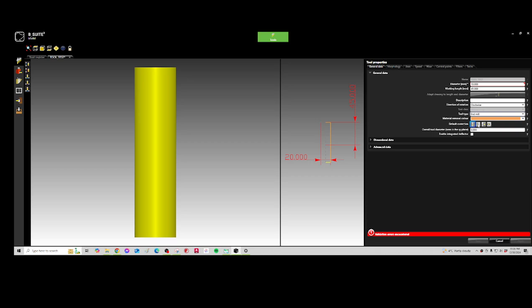If you put this, it's going to work from the left, this one from the right, and this one from the geometry. Usually I'll leave it here because this is just a default correction. You will have to set this up every time at the moment that you select the tool. When you select the geometry, make sure you select left, right, or center from the geometry. Okay, overall diameter.